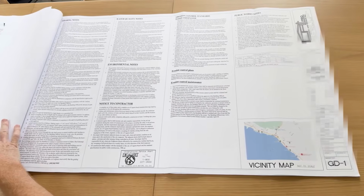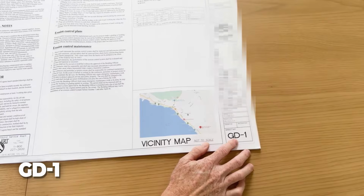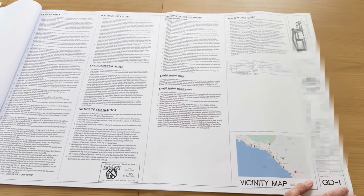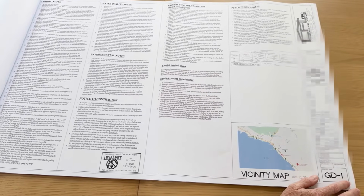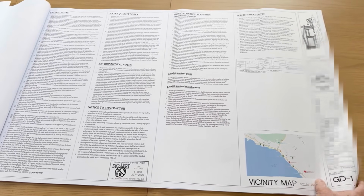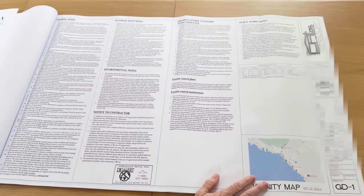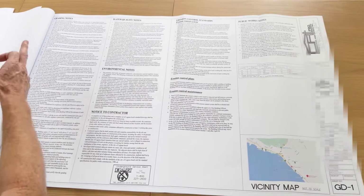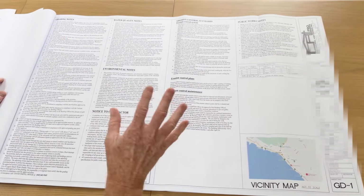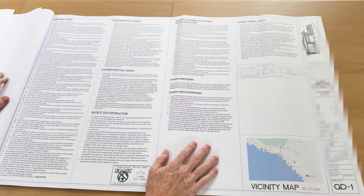So next page here, guys, as you can see, this is our grading plan, or we start the grading plan set phase. Okay, so in this case, there is a grading plan. Grading plans are a specific set of drawings that ensure that if we're removing dirt or earth, that we not only account for special requirements, but it's specifics on how to do so. Okay, so lots and lots of information, as you can see, but this is grading. GD stands for grading. Okay, lots of notes. You're going to want to read through all these, and again, this might not apply to every set of drawings, but in this case, it is.